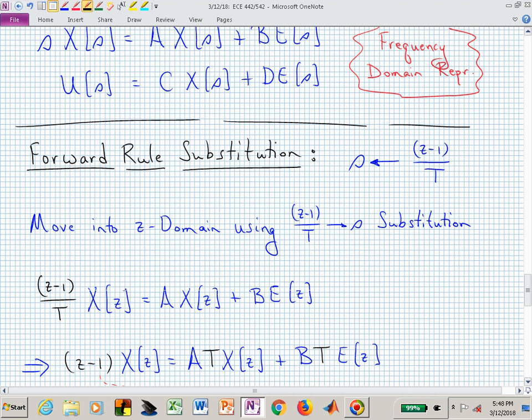If it was a second order system, then A always is square. It would be a 2 by 2. And you would simply scale every entry, all four entries in that 2 by 2 matrix, by the sampling period capital T to give you AT.